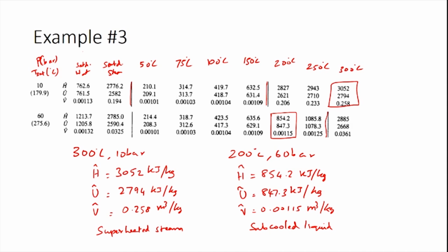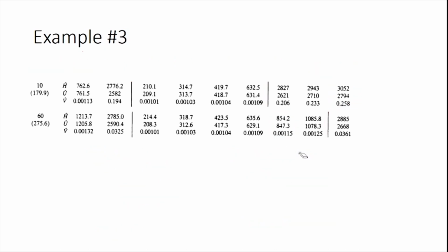So, this indicates that the specific volume of steam, which is much higher than the specific volume of liquid water, influences the change in enthalpy. This is an aspect which we need to understand and which we can appreciate directly by looking at these values from the steam tables. Let us perform the calculations for finding the difference, so that we will get the answers required by the problem.